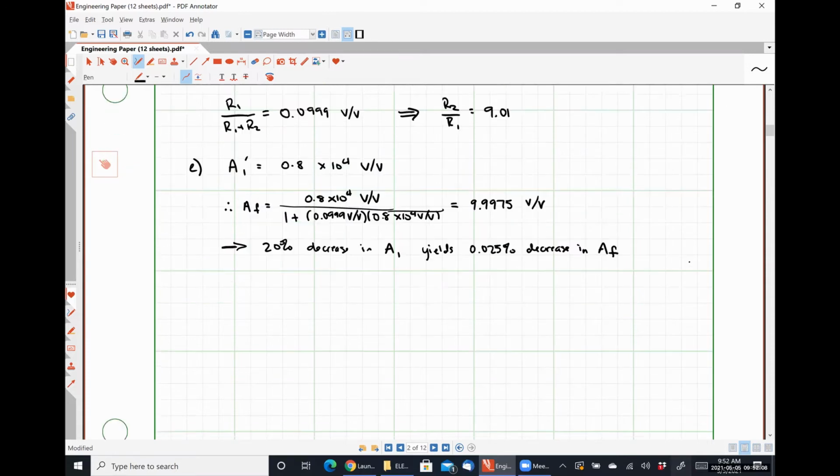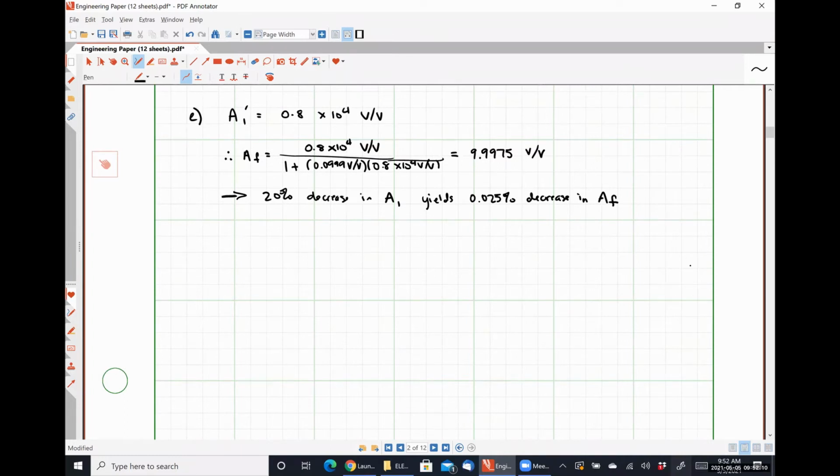Okay. So we are literally just seeing what the effect of changing our open loop gain has on the performance level of our closed loop gain. And so with that in mind, where we're holding our feedback factor to be constant, we can develop a pretty simple relationship, okay?